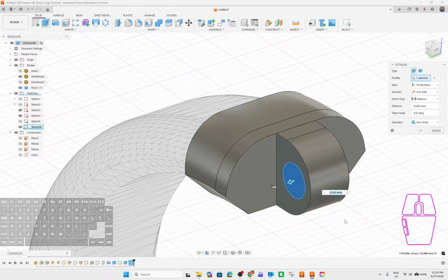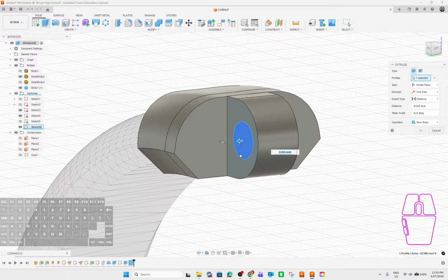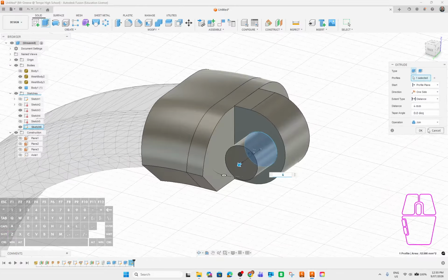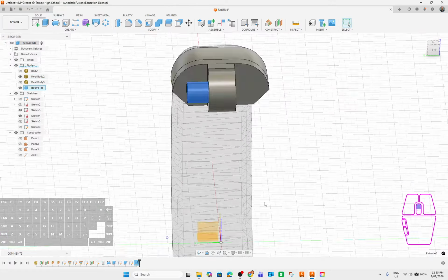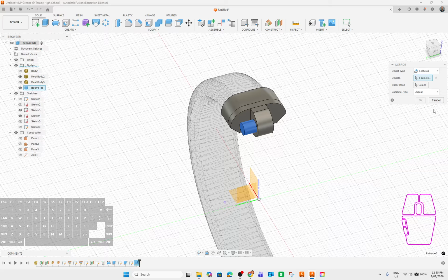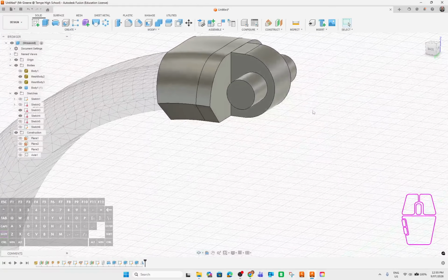So we're going to go here, extrude that out, and we're going to go a little bit into this area. So 5 mil, too much, maybe 4. Yep, that should be good. We'll go OK, and then with this process, I could sketch another thing in the same spot here, but I also have these mid planes as reference, so I'm just going to mirror this feature on the other side. So features, that's the feature I want to mirror. The mirror plane is here, and I'll make that identical. Yeah, so that's the main part of my print-in-place hinge there that makes it functional.